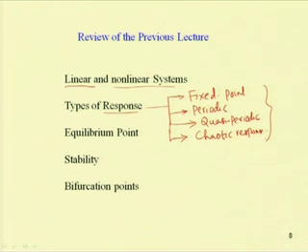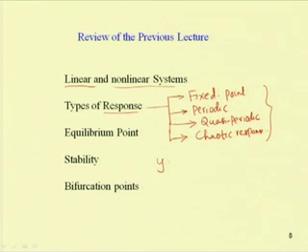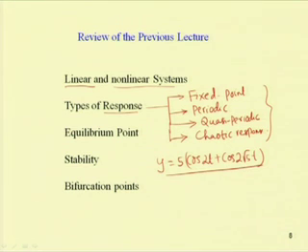In case of quasi periodic response, it is an aperiodic response in which the different frequencies bear irrational ratios. For example, I can write the response y equal to 5 cos 2t plus cos 2 root 5 t. The resulting response will be a quasi periodic response with frequencies 2 and 2 root 5, and the ratio between these two, that is 2 root 5 over 2, which is root 5, is an irrational number. So, the resulting response is quasi periodic.